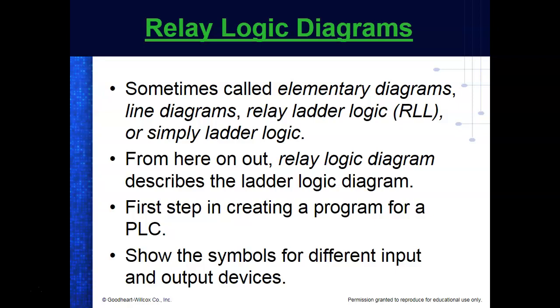They probably pull about 10 amps, and there's no way in the world those lights are going to be run by that little switch in there on your car. So when you turn on your lights, it goes to your module control computer. It has a relay that it energizes, and then the lights are turned on by that.